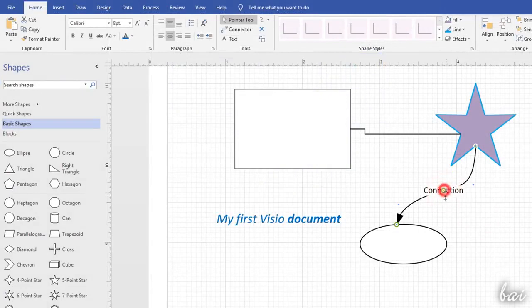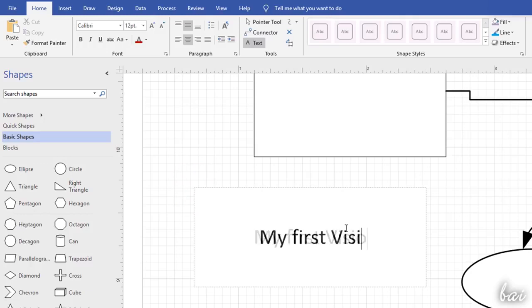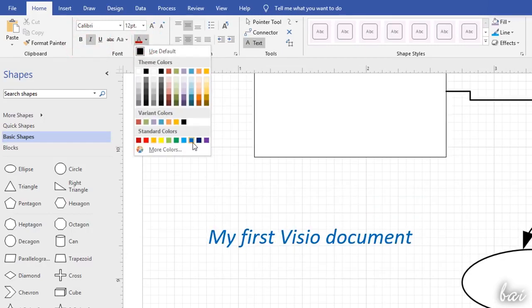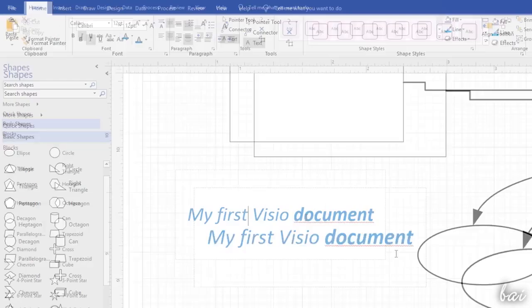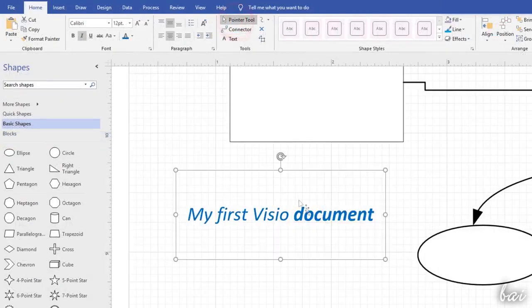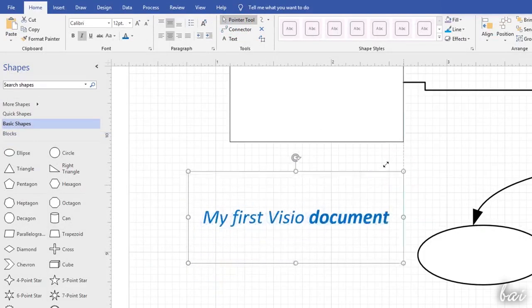Text is added to describe or name the several shapes you have built. With the Text tool enabled, click and drag on the document to create a text area which delimits the content you type inside. Then, adjust the text color, font, size, style, and distribution under the Home tab. These modifications are applied on the whole text unless you select just a piece of it. The piece of text created can be moved, scaled, or rotated independently as seen for other objects before.